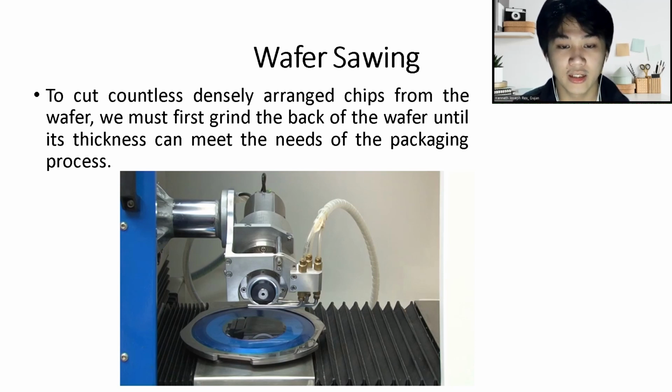First is blade cutting, second is laser cutting, and third is plasma cutting. Blade cutting refers to cutting wafers with diamond blades, which is prone to generate frictional heat and debris, and thus damage to the wafers. Second, laser cutting has higher precision and can easily handle wafers with thin thickness or small scribing line pitch. Plasma cutting uses the principle of plasma etching. So even if the scribing line pitch is very small, this technology can also be applied.